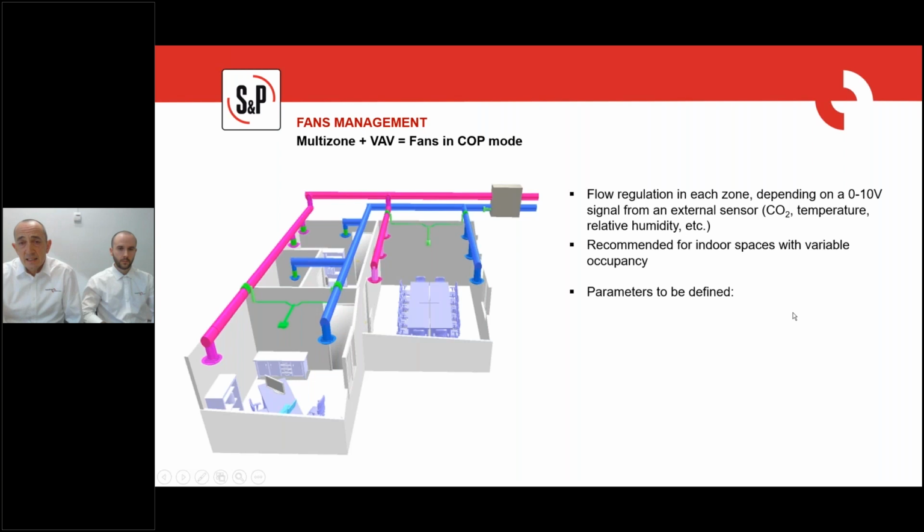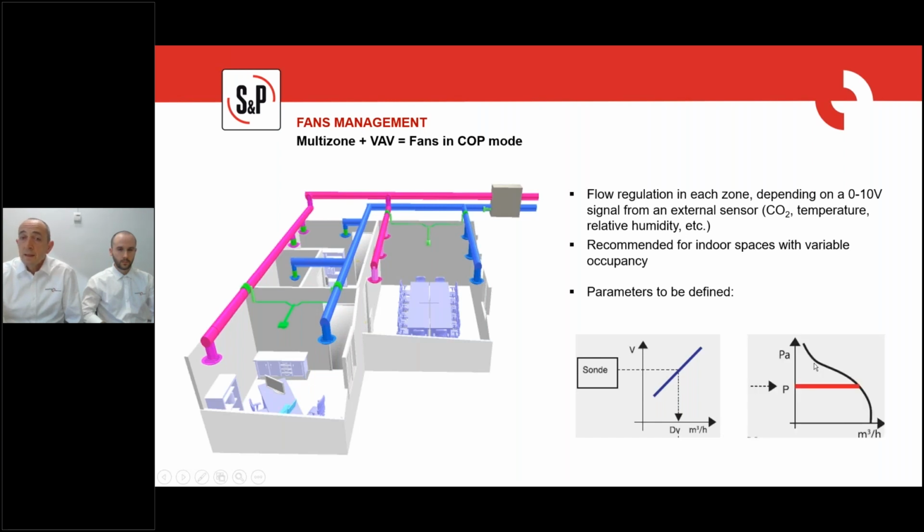Well, this system is composed also. Here you can see the sensor or the graphic to see the relation between the sensor and the opening of the damper, which at least is the airflow which is being delivered to the room. But in this case, we need also to control the pressure in the fan. So the demand finally is measured by some pressure transmitters.